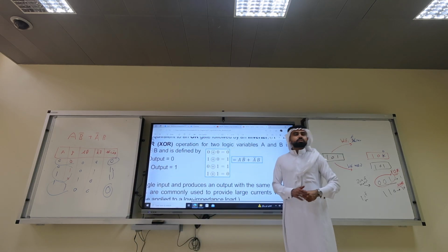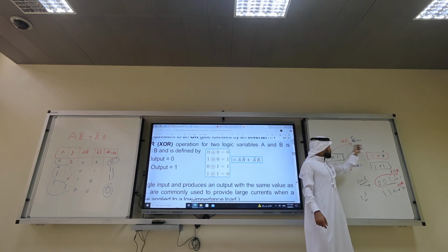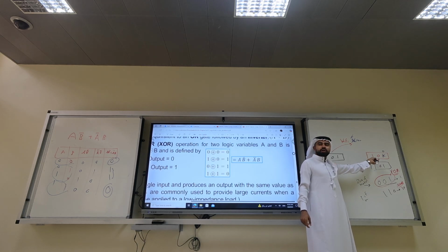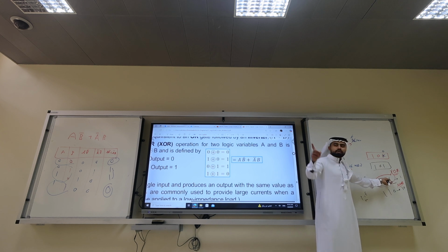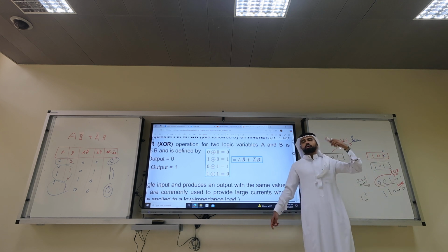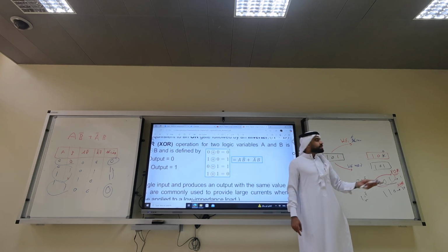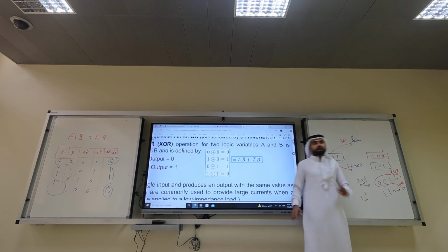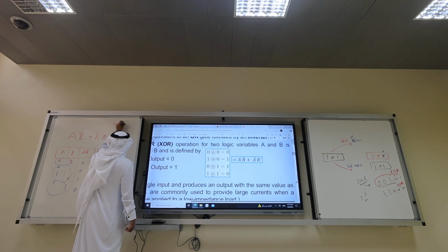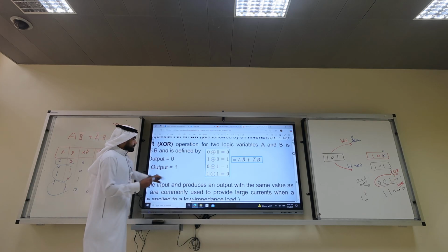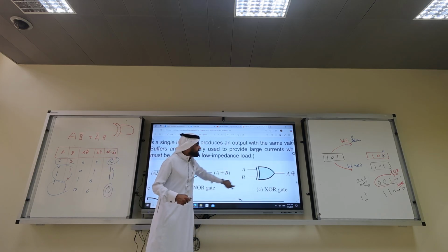So XOR, what it does, remember the signal 101 and 100 that became 100 and 101. If you get 001, you have 1 error. So if they do not match, report a 1. If they match, report 0. This circuit, the XOR gate, is very, very important. And its symbol is what? It is OR with 2 brackets. This is its symbol. Okay?